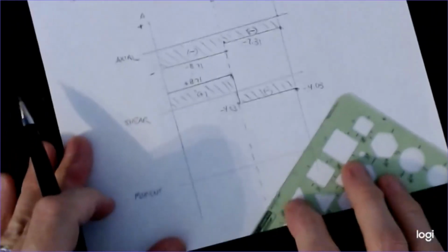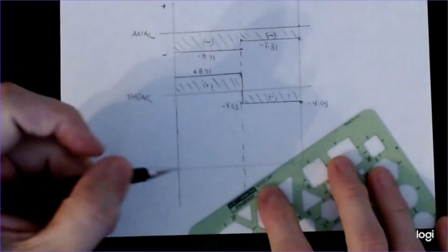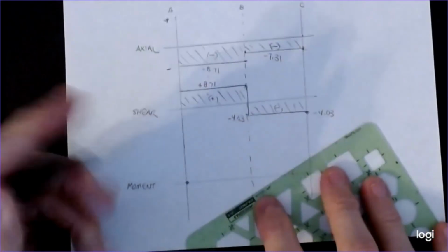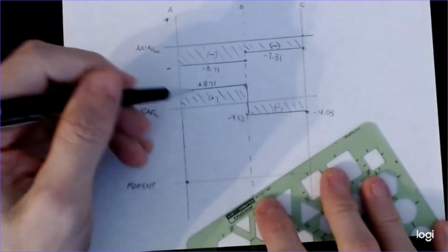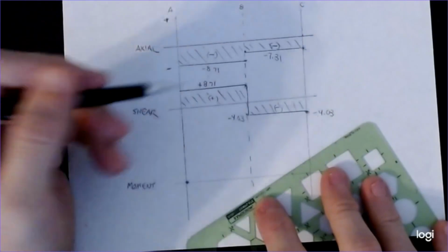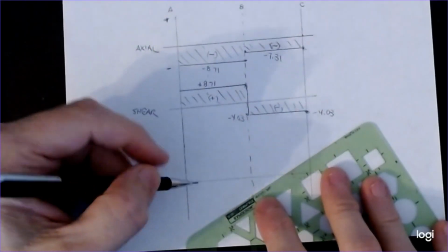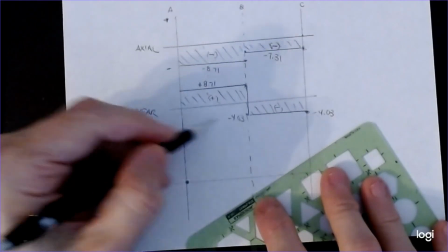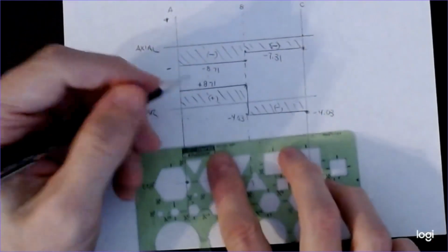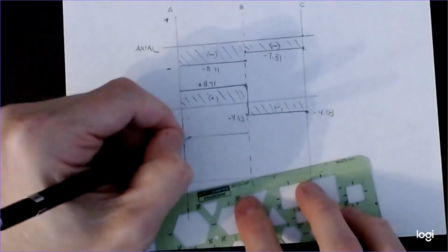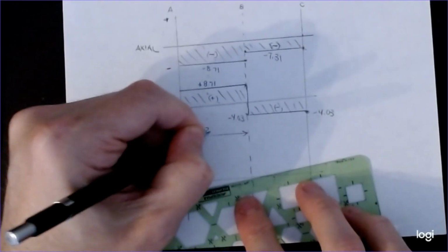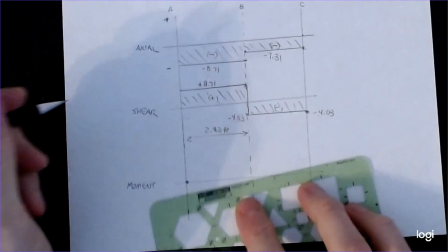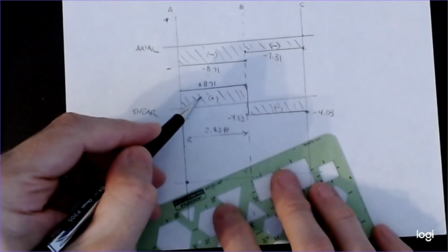All right, and then the last piece is we're going to do the moment. It was a pin support, so it starts out at 0, and now all I need to do is look at what the moment diagram is doing relative to this. We look at the amount that it goes up. It's going to be 8.71 times that distance, which is 2.82 feet. Again, our distance here is up on the upper picture, but I'll draw it here so we remember 2.82 feet here. And so this is a constant load.